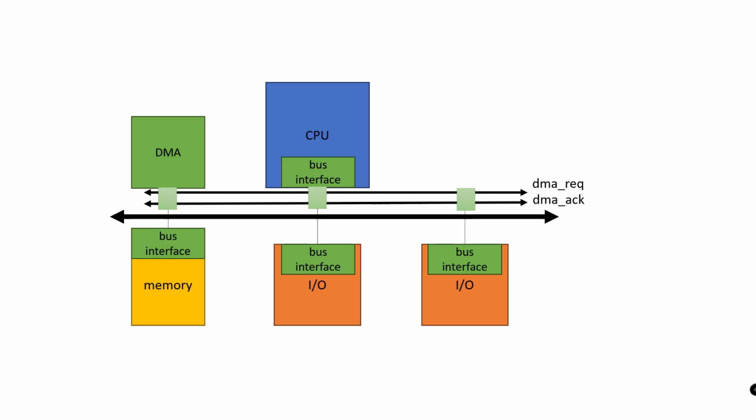The CPU gives parameters for the request of the DMA unit, which performs the request and then tells the CPU that the request is finished. The CPU can't use the bus while the DMA controller is performing the operation, but many DMA controllers can be programmed to limit their utilization of the bus to avoid locking out the CPU.